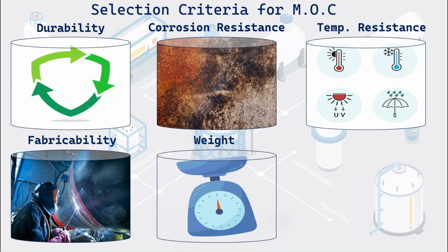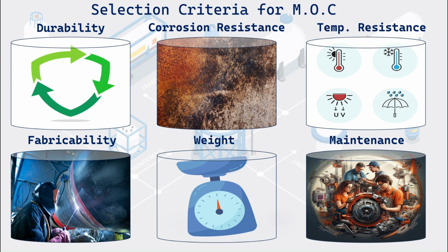Weight. Materials like aluminium and composites, for example, fiberglass reinforced plastics, offer a high strength-to-weight ratio, reducing vessel weight, but will have limitations in temperature and pressure resistance. Service life and maintenance. Materials with better corrosion and fatigue resistance generally extend vessel lifespan and reduce maintenance needs. The better the grade of material used for construction, along with non-abusive usage, ensures performance of the equipment will be maintained for longer time, thus reducing maintenance breaks.